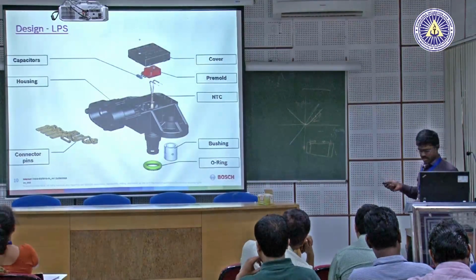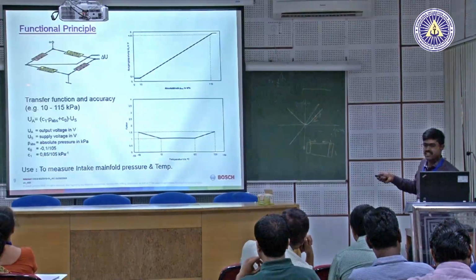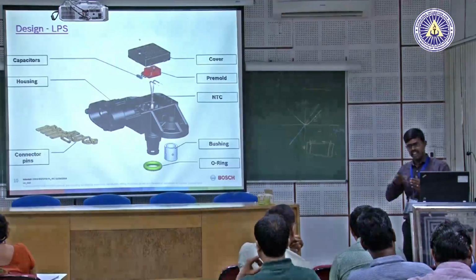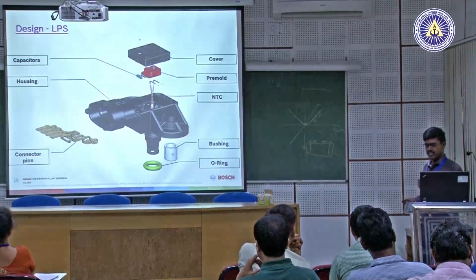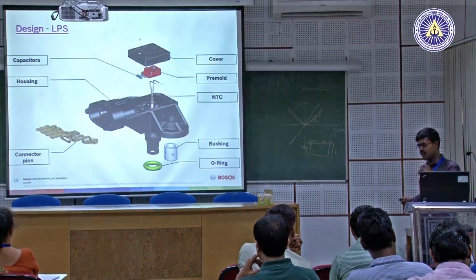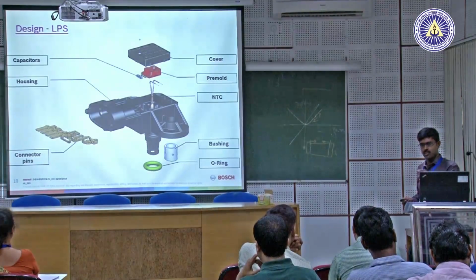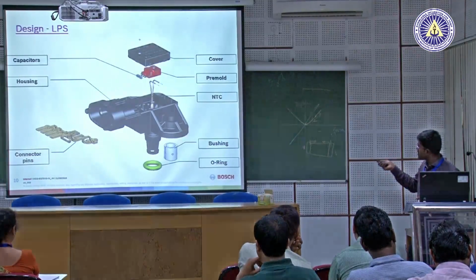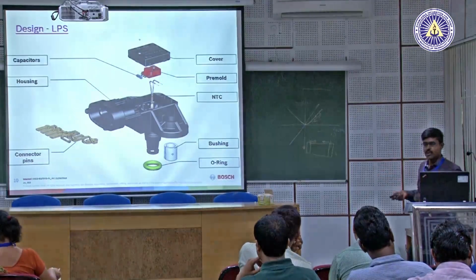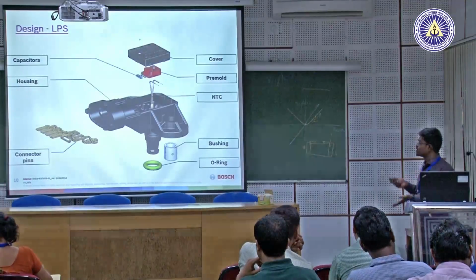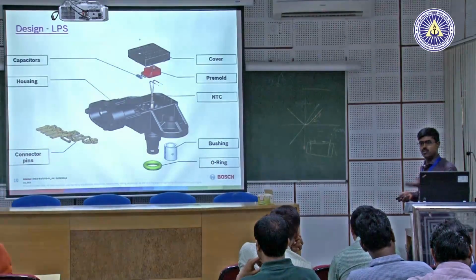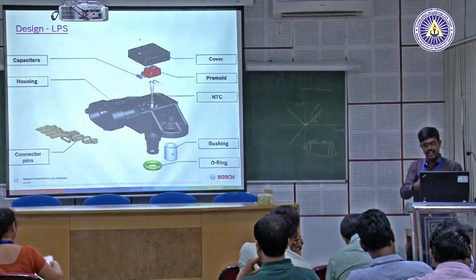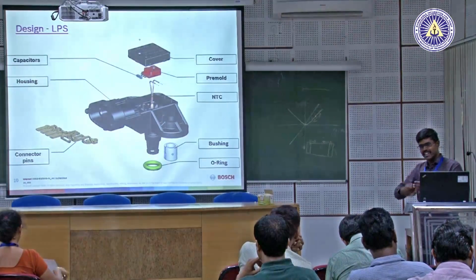In that circuitry this fabrication is done, it is very minute, with many layers, and we use very small resistors, pressure transducers, and these are all fabricated. In that pre-mold you have different layers. In those different layers, one is again a vacuum chamber, a small chamber. If I go into details, I can take one sensor.